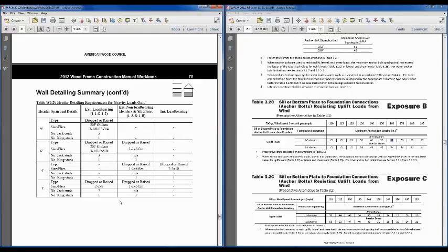For the anchor bolts, I think there is an exception in the code specifically for half-inch or greater anchor bolts, but I don't know that any exception like that exists for wood structural panels, and so that's a real issue that if you're driving nails in your shear walls into treated wood, into sill plates, then you need to make sure you're using the appropriate fasteners for that.